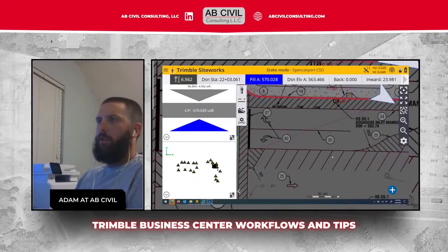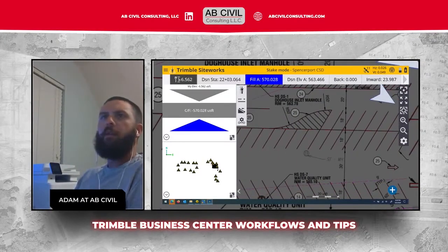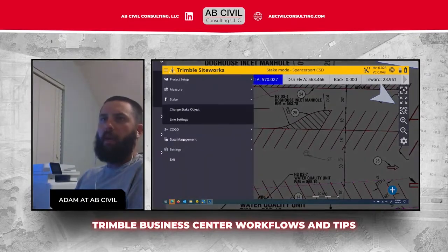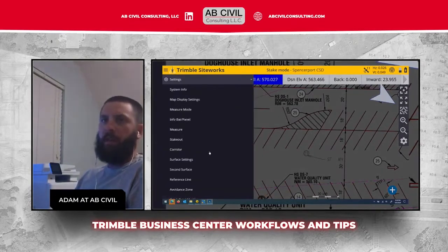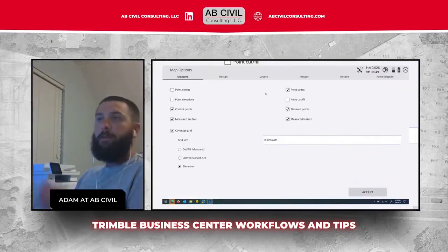Yep. So now all those arrows are gone. Sometimes the contractor gets annoyed at seeing those arrows in their design. I like seeing them if I'm staking anything. It makes a lot of sense to know where your water's flowing in, and it helps catch if there's a mistake in the surface, a mistake in the design, or if you have to adjust a box or something and move a box around. It helps to see that.